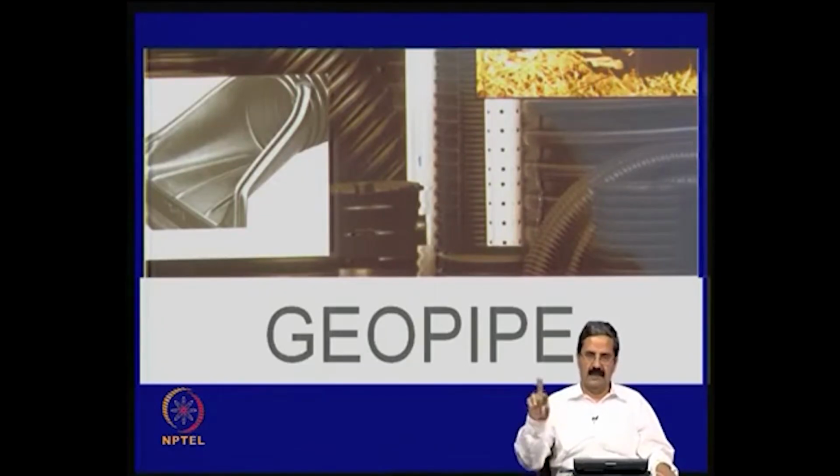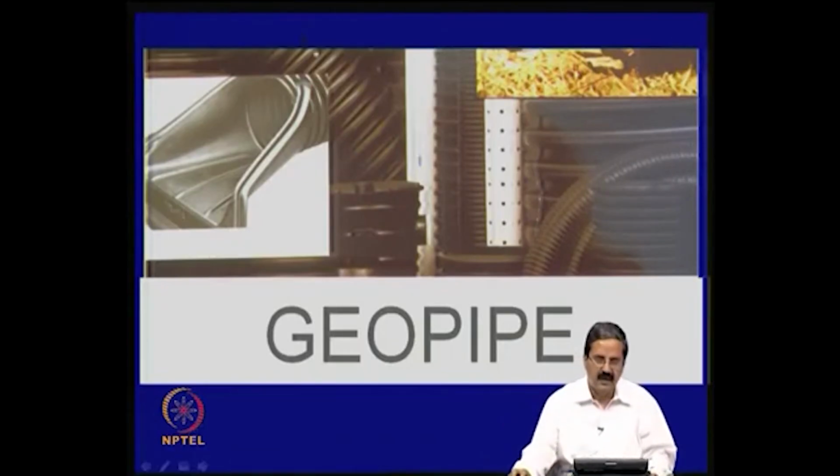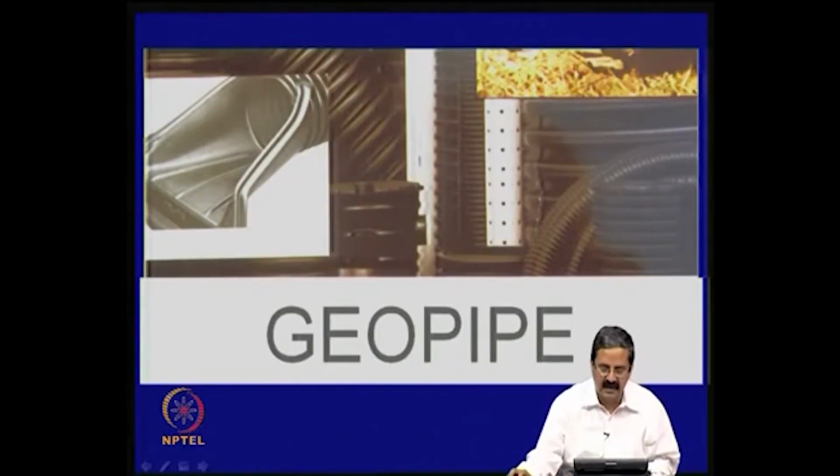flexible pipes, because of the soil structure interaction, the load whatever is applied will not be totally coming onto the pipe. Because of the soil arching and other conditions, the load may be much less than what you expect using gamma B into height, into that particular 3 meters, say for example. It will be much less because of the interaction. Okay. So, arch action is taking place because of that.